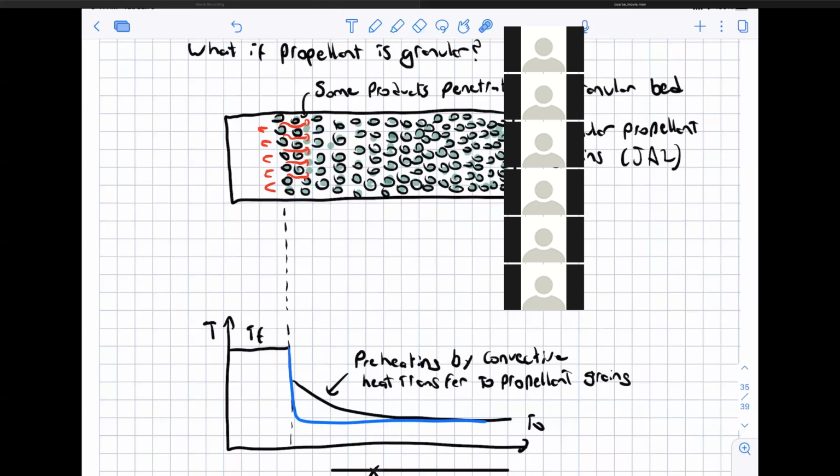But they have to ignite first, and solid propellants do not ignite via pressure. Does that make sense? Yeah, so you need the preheating in order to get them to a state that they're ready to auto-ignite, and then once they ignite, the pressure effect can take advantage of that.